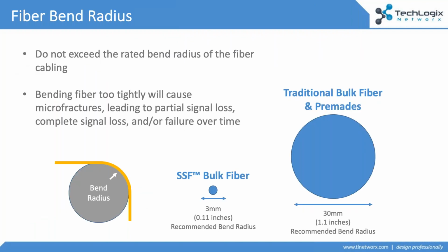Final thing that I want to touch on here before we take some questions is fiber bend radius. This used to be a really, really big deal in those fiber installations, right? And if you ask people who were installing fiber a decade ago or 15 years ago, they'll tell you fiber is incredibly brittle. And the problem is you might be pulling it, and you kink the line or you pull it too hard. It wasn't the fact that your fiber would break right away. It's that it would fracture and then degrade over time.